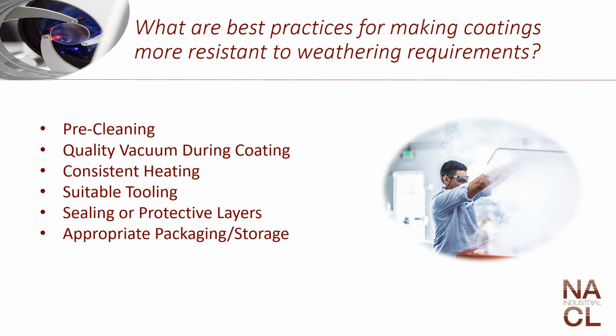As I mentioned, glass expansion and contraction during the coating process, that needs to be compensated for in your tooling. Again, if you hinder glass from expanding and contracting in your tooling, then not only can you break your optic, but also you might hit a softening point, you might have some heat transfer, which will change your surface figure, which will then invariably affect your adhesion and weathering performance.